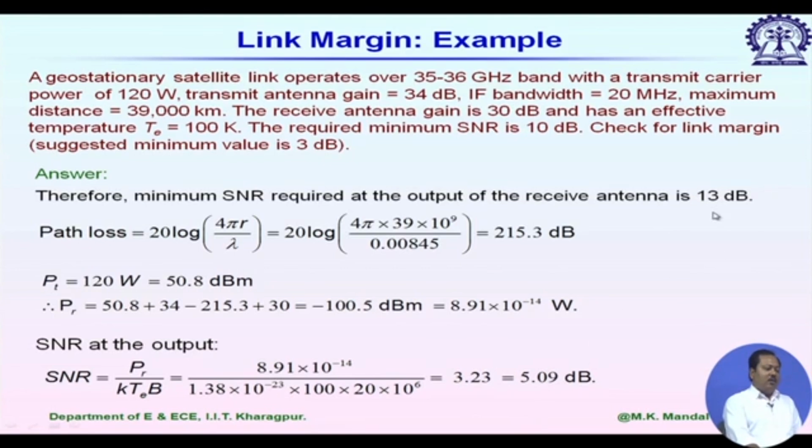So, the only control we have is that we have to increase either the transmit power or the antenna gain. It can be the transmit antenna, it can be the receive antenna, but we have to increase the gain. And another interesting thing, the noise depends on temperature. So, we can cool down the receiver to decrease the noise component. So, these are the external controls we have.